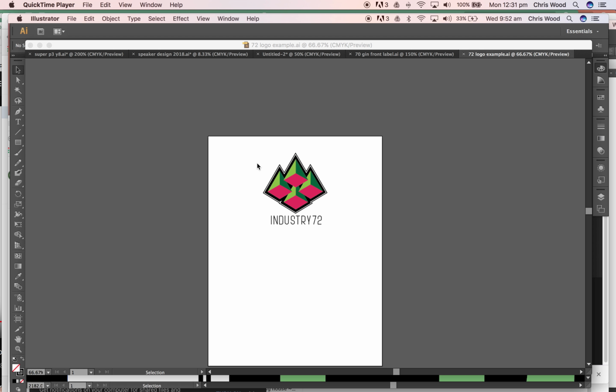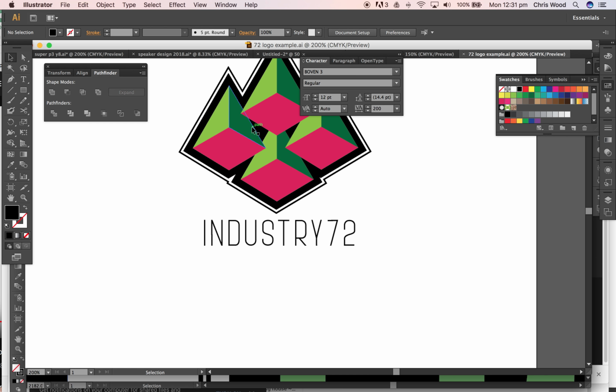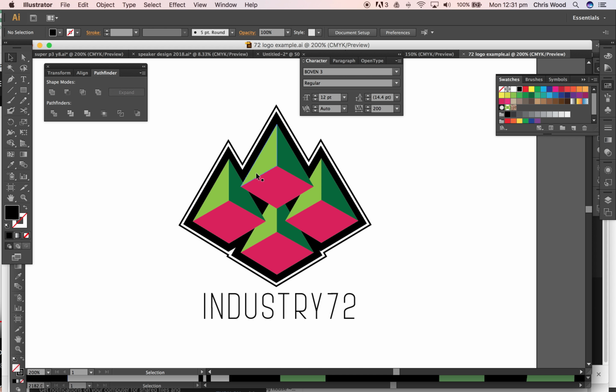Okay, hi everyone. Today we're going to have a look at getting a logo out of Illustrator and into Blender specifically. Okay, so I've got a bit of a logo here and let's just get in and have a look at it. So I need to do a little bit of cleanup on this particular logo to make sure that it works in 3D nicely. So things like we don't want to have overlap because that can be a bit of a problem. Okay, so we're going to use the Pathfinder to get rid of that.